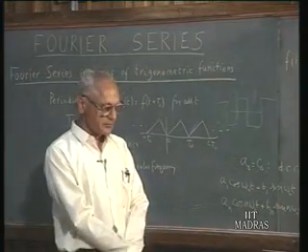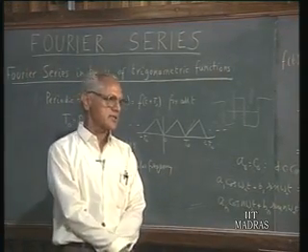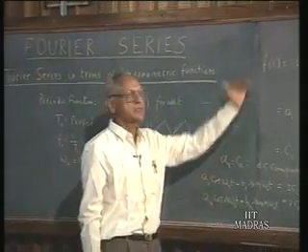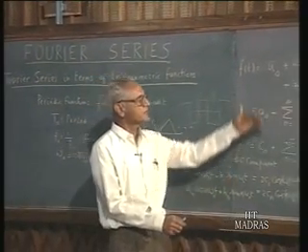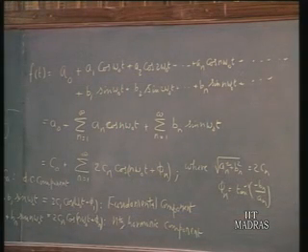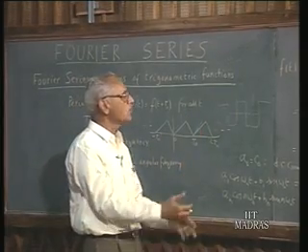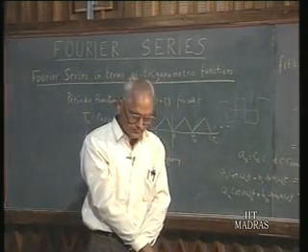That is the basic idea of the Fourier series as far as circuit analysis or system analysis is concerned. A given composite periodic function can be resolved in terms of various sinusoids, and we know if there is a sinusoidal driving force, we can find out easily the steady state response, and therefore we have a large number of terms. For each sinusoid we find the response and add all these responses to get the total response. So it is in this context that the question arises: if we have an infinite number of terms, how are we going to grapple with this?